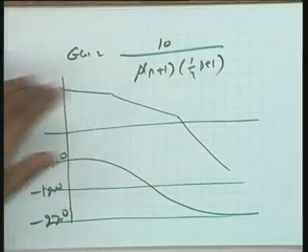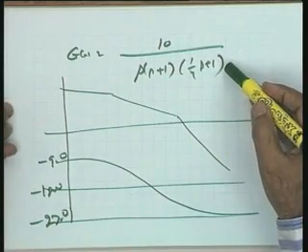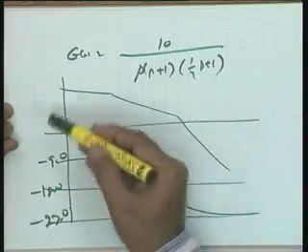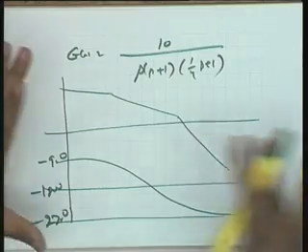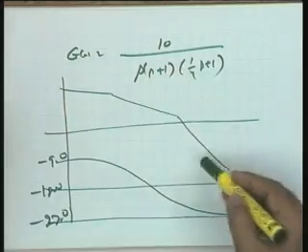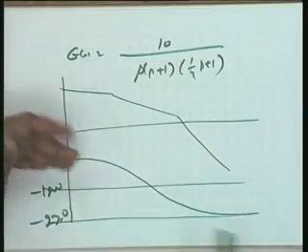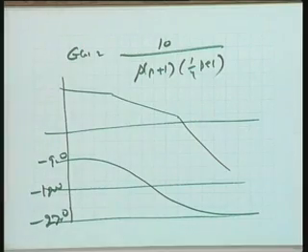Given the open loop frequency response data or the open loop transfer function, I will first make a Bode plot. I feel that this hardly needs any calculation, because an asymptotic plot with dB corrections can be made, and for the angle, if I have the two asymptotes and a couple of points in between, I can again make an approximate angle plot.